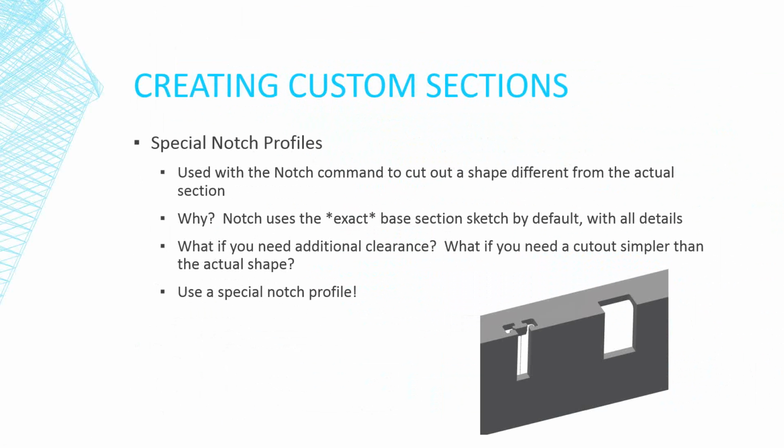Now the notch profile is used specifically with the notch end treatment, which if you're not familiar with that, we'll discuss that in a little bit. But ultimately it's where you're cutting a shape from one member as relief, almost like coping against another member. By default, it's going to cut line to line the exact shape of the member. So you can see, in this picture here,